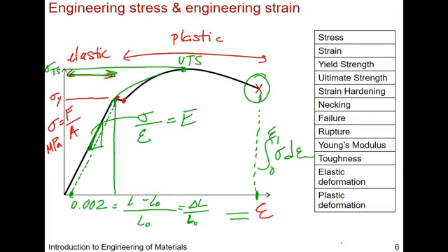And then what we've been talking about before is plastic deformation, when something will go back to its usual crystal structure versus when it will not. So those are the two regions that we'll focus on a lot. Oh, and then of course there's ductility as well. So the ductility is just, if you extrapolate this with the same slope, the strain at failure times 100 gives you ductility, which is not on this list.